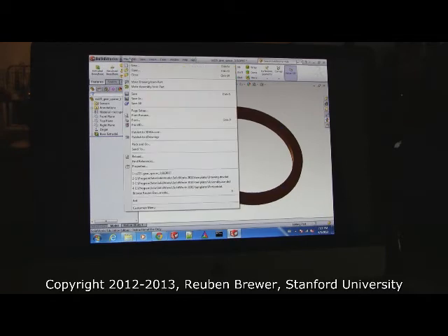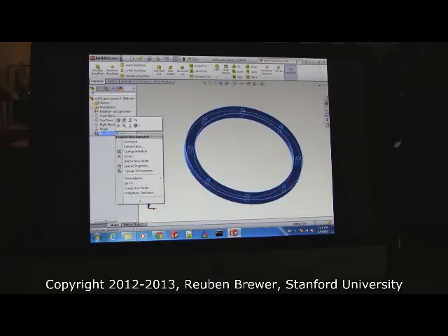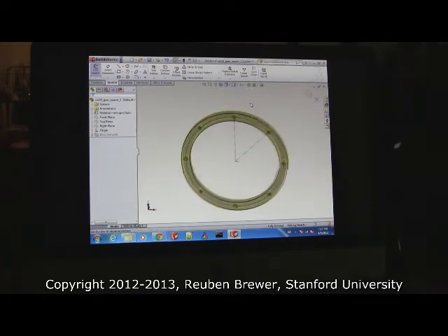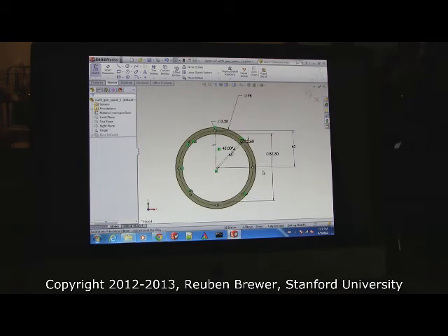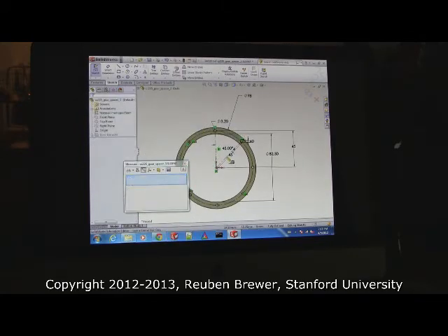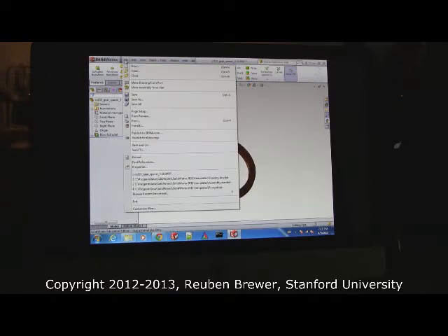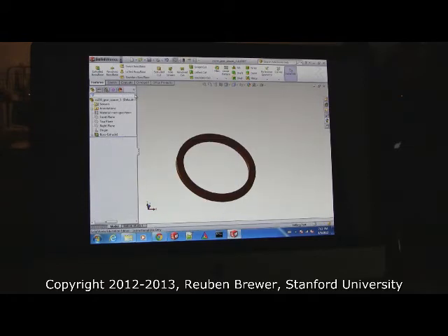Can I just point out something? Yeah. When you're editing a sketch, at the bottom right-hand corner, it actually does say if you're fully defined, under constrained, or over constrained. Right where it says editing part in the lower right-hand corner of yours, see it says fully defined. Hey, very well done. Okay, thank you. The errors just pop up, and then it will highlight in light blue. Don't worry about that. So everybody save that. That part's done, and that is one of the parts from your homework.